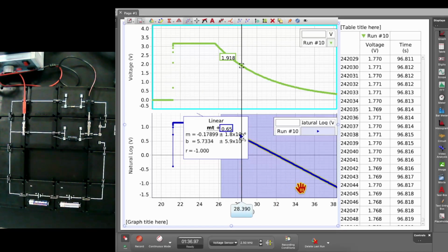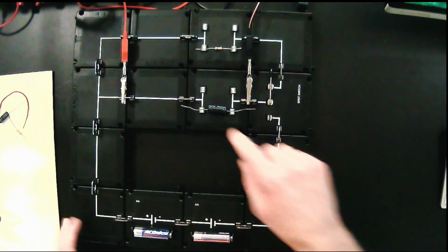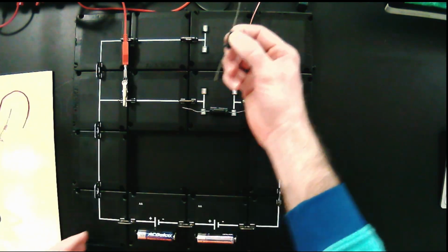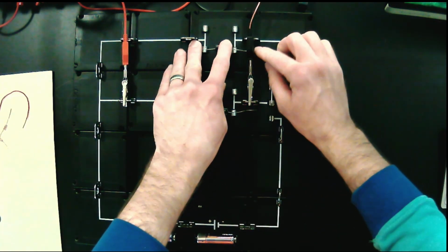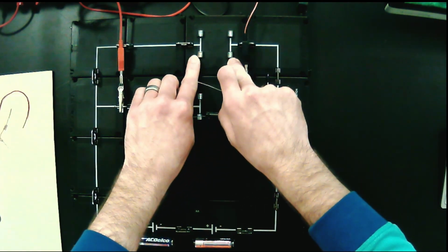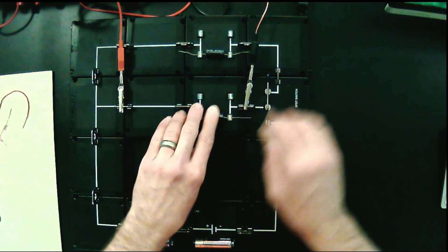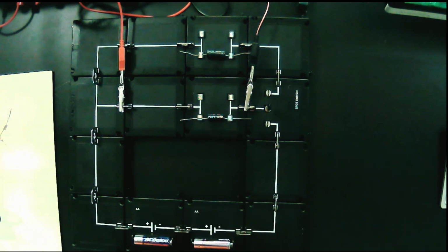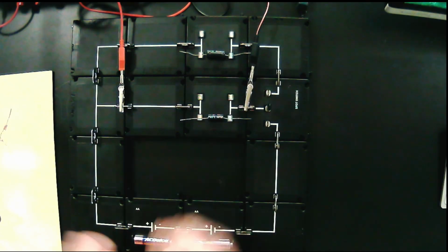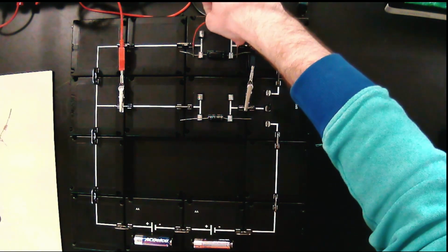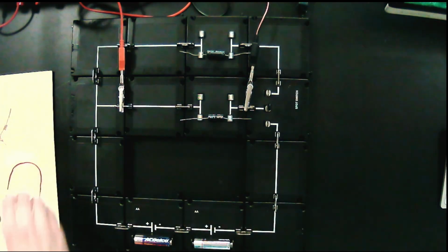Then the second experiment is now, instead of having a capacitor and resistor, we take the resistor out, take the other capacitor here, and throw it into the top set of springs. I'm going to switch them for demonstration purposes. You don't need the resistors anymore. To start, before you take any data, use the red wire, discharge both of the capacitors just to ensure that you're starting out essentially fresh.